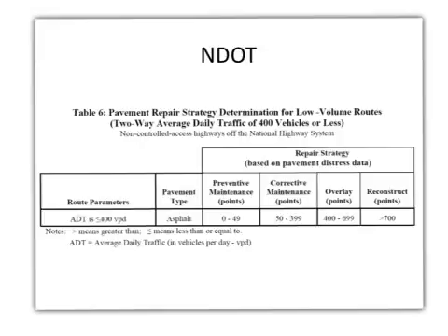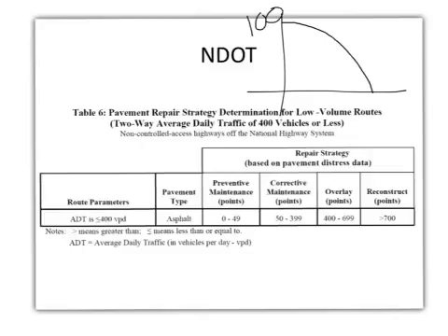For example, the PCI system goes this way. A good pavement is going to have a PCI of 100, and it's going to keep failing with time from here all the way to here until we reach failure. The failure is at about 30 or 35 as a value of PCI. The Nevada DOT way is kind of the opposite, where they keep accumulating the cracking points as well as rutting points, and they do not subtract from a grand total of 100.